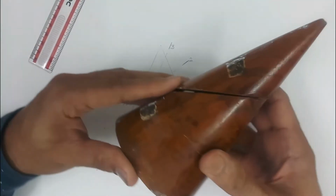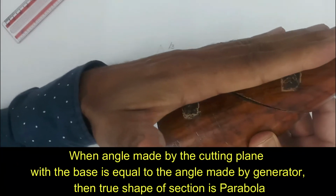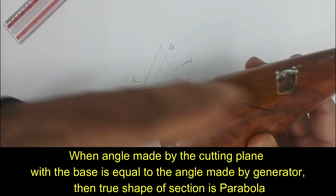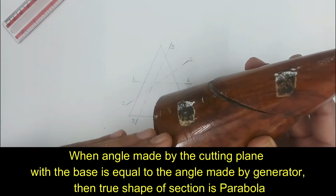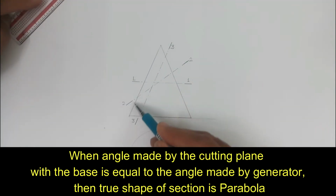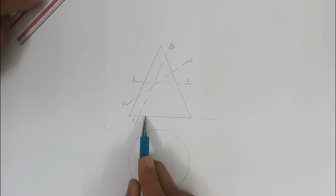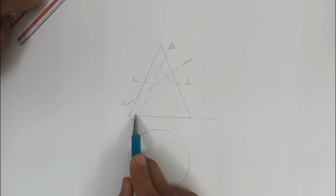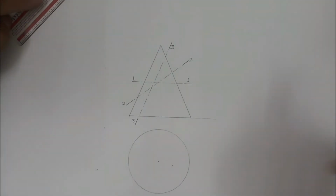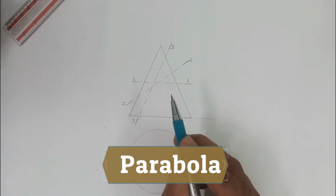Let us think of the third possibility. If I cut this cone by a cutting plane which is making the same angle as that of the generator, that means now the cutting plane is parallel to this end generator, so it is cutting something like this. On the drawing it is represented something like this. So we can see this is the end generator or simply generator, and this is the cutting plane. The angle made by this cutting plane with the base and the angle made by the generator with the base are the same. In this condition we get the true shape of section as a parabola. So section 3 3 gives the true shape of section as a parabola.